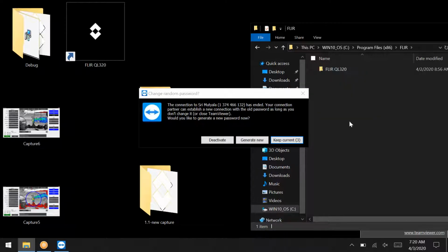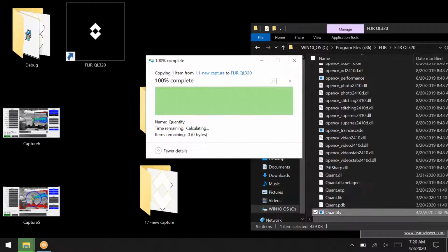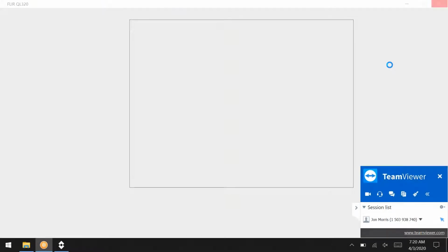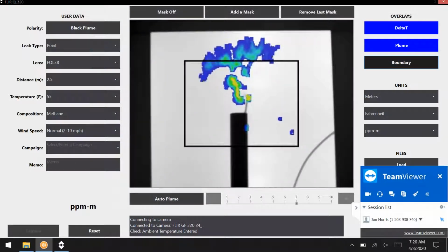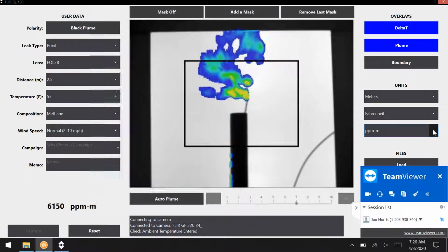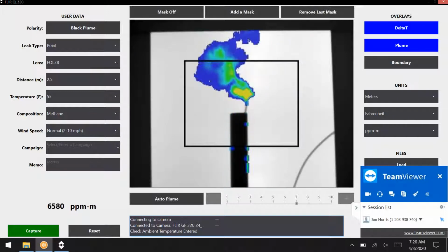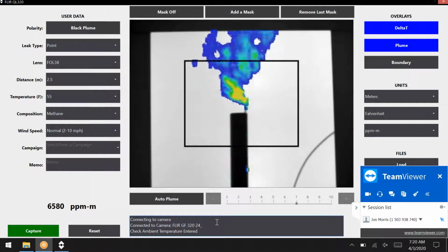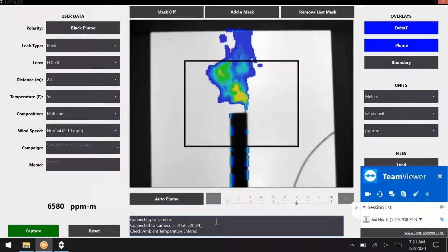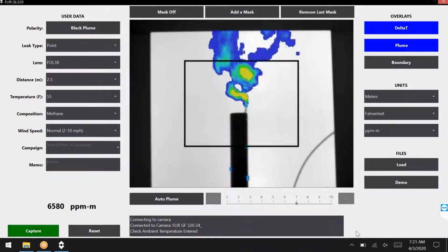I believe what John's talking about is we wanted to present to this team, as the leaders in the optical gas imaging and oil and gas world, what if the QL320 did not have any updates? It just spit out a number. So you have a video like John's showing here, nothing happens. And then once you have a number that is ready, you simply save that. And I think, John, ideally that number wouldn't change like it's doing now. In this, you'll notice you had it updating after 5 seconds. I would change that to it does not update until it's ready to capture. But once you get a number, there's no changing, there's no ambiguity, there is just a single number that the user can save, and then they can hit reset or start over with this exact same thing.